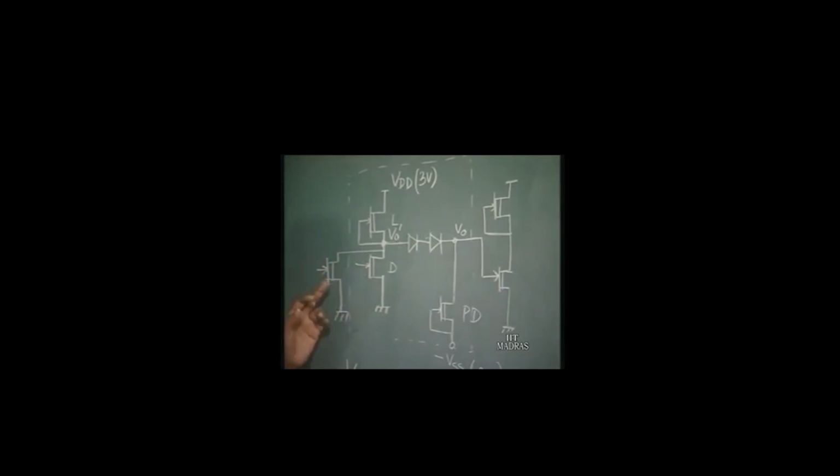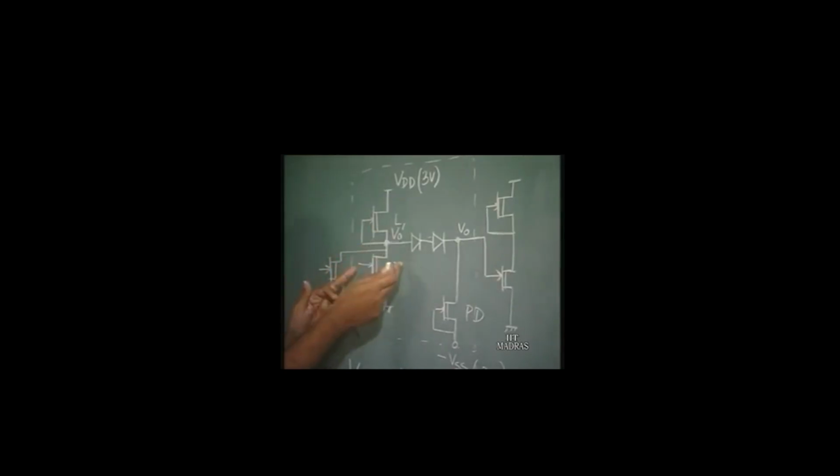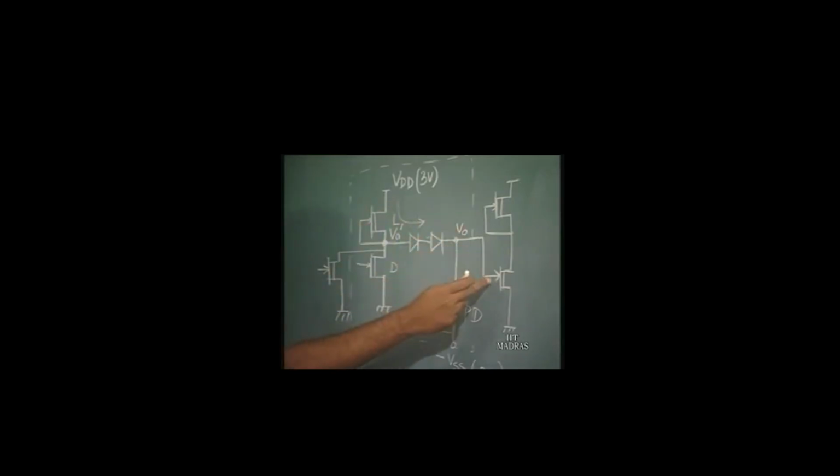Now, on the other hand, when we look at the pull up configuration, that is when both these transistors go off, then what happens is the pull up is taken care of by this load transistor. So the load transistor must drive a current here in order to charge the output voltage, or turn on the output transistor here, the next transistor. So it has to supply a large current, but since the pull down transistor is always on, a large part of the current flows into the pull down transistor, and thereby the delay is quite high.